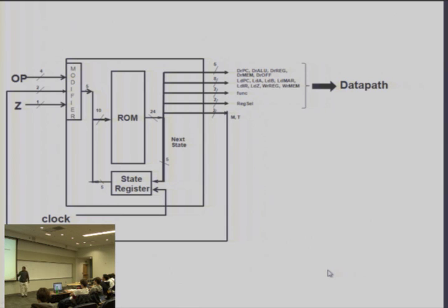So in that sense, you can take each one of those outputs that you see, and go back to your sequence and say, well, what is the logic function that is represented by that, and create a combinational logic circuitry that implements each one of those functions, right? And this kind of design is what is called a random logic design. Or it's also called hardwired design.